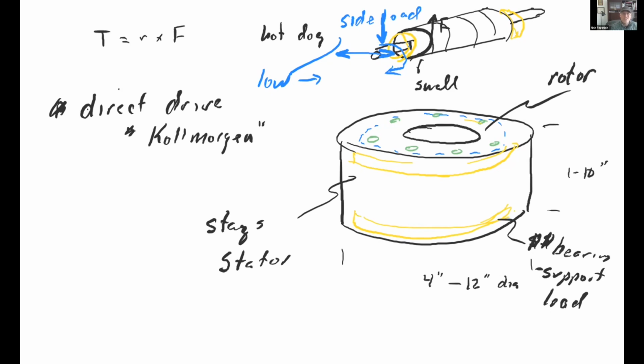The reason we actually use these in 140 instead of NEMA 23s all the time is because the students end up designing things that need a fair amount of torque, but they want to attach directly to the shaft. And rather than do a whole separate bearing structure and couplers to properly do the loading, we just bought some fixed couplers from Ruland. Actually, they donated them. And you could attach your stuff right to this shaft.